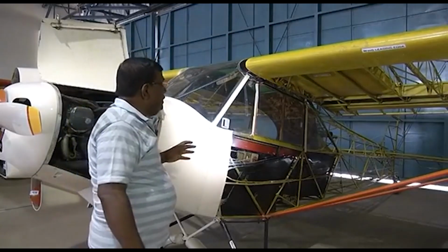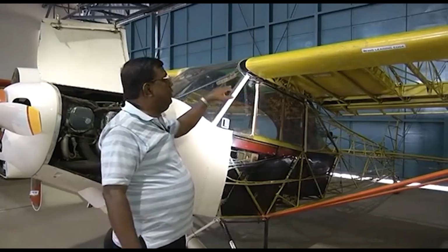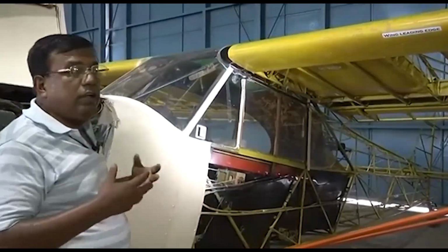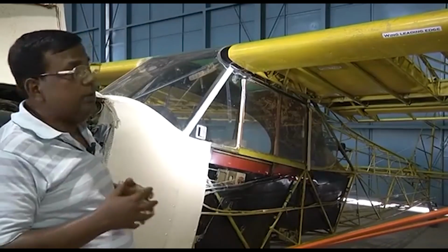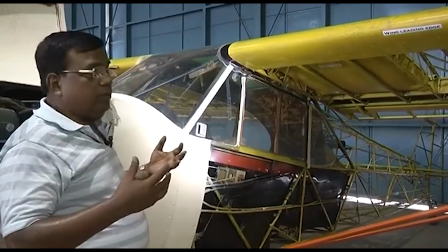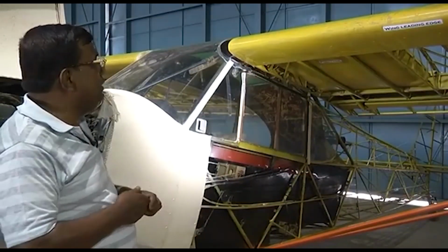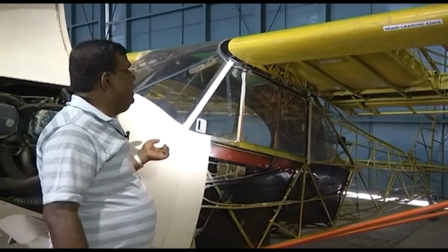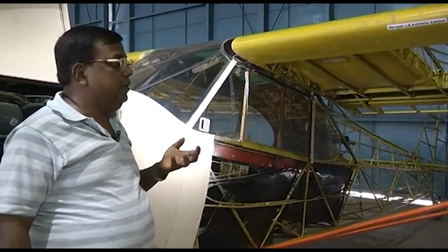The most important thing we should understand is that we need to cater some space for fuel. The moment I put in a fuel tank, not only is the weight of the fuel important, but it is also important that the fuel tank is leak proof and its weight is not very high, otherwise it will change the wing loading. Also we need to know which fuel pump I'll be using, and the reliability of the fuel pump is extremely important for good performance of an airplane.